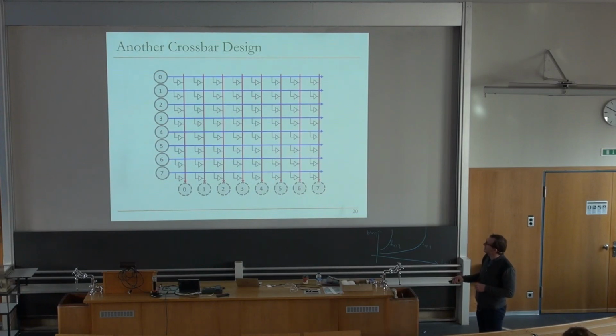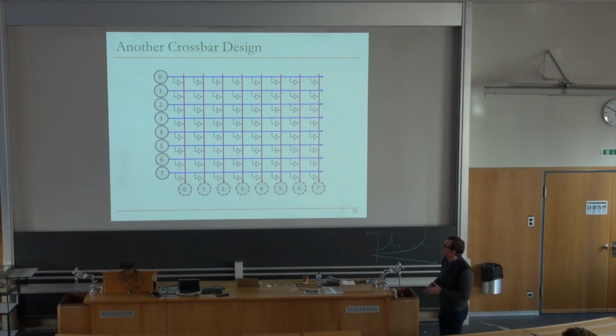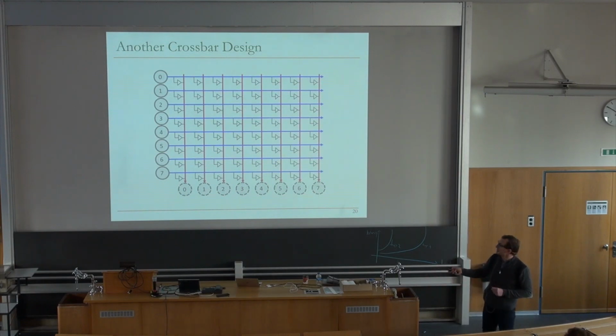So this is another crossbar design. This is actually interesting. Basically, this shows the arbiters over here. If you're transferring from 0 to here, you need to ensure that you arbitrate across the shared link somehow and decide which one is loading its data onto the shared red link. And you could build it in different ways. You could have a version that has buffers over here that buffer the data that's supposed to be sent from 0 to, let's say, 0 over here. You could have a version that doesn't have buffers.